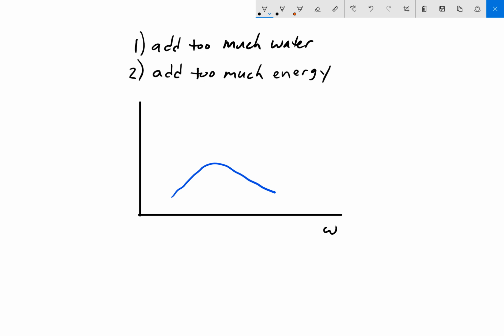This is moisture content. This is dry density on this axis. There we go. Now, for a given moisture content, say this value right here, you can see that I fall on the dry side of this compaction curve. I am less than the optimum moisture content.